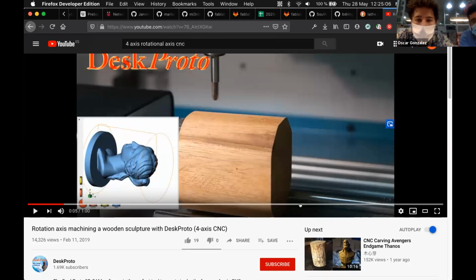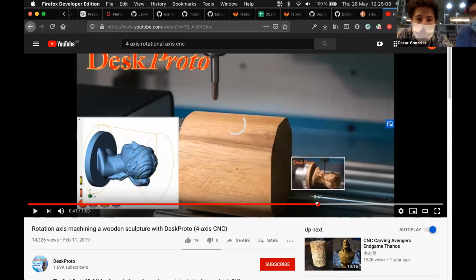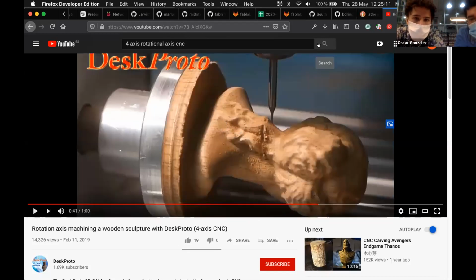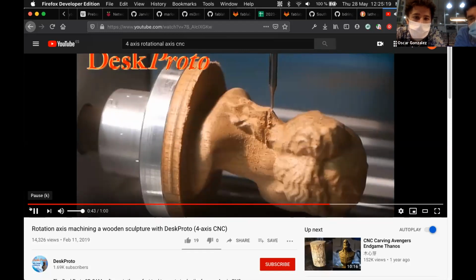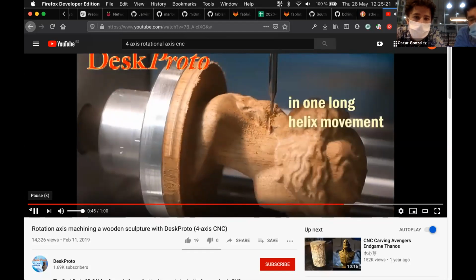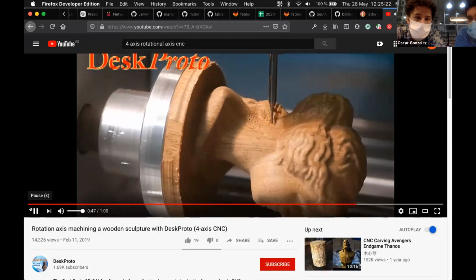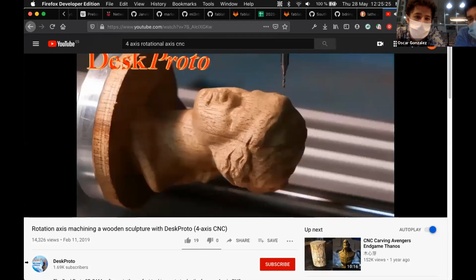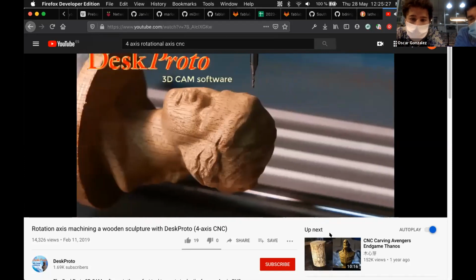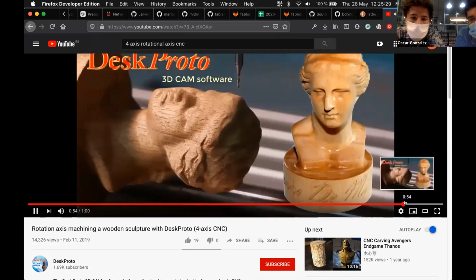For example, you see an end mill cutting at high speed, but we have a fourth rotational axis that allows making really three-dimensional parts by mixing both movements. And how you make the G-codes for it, don't worry too much, because RhinoCam also produces 4-axis milling with rotation. So that's what we should be doing.